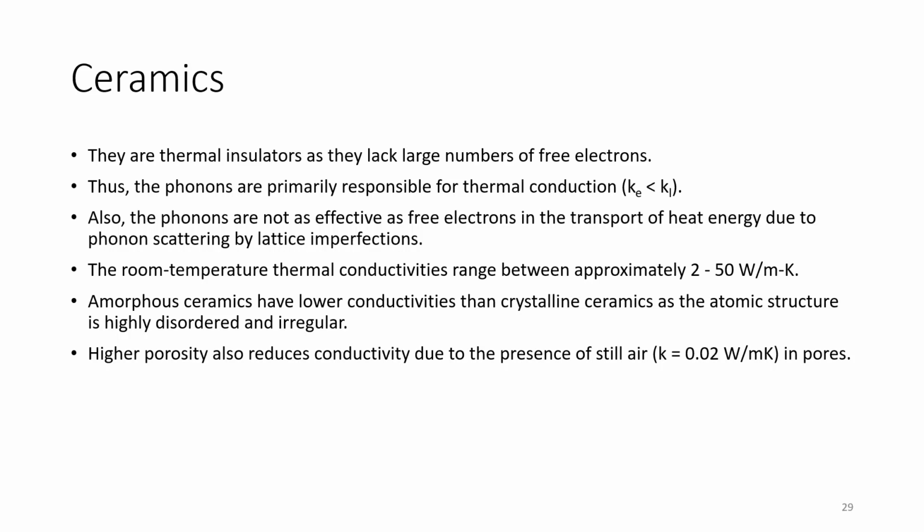Next are ceramics. They are thermal insulators as they lack a large number of free electrons. Thus the phonons are primarily responsible for thermal conduction. In this case conductivity because of electrons is lesser compared to conductivity because of phonons. Also the phonons are not as effective as free electrons in the transport of heat energy due to phonon scattering by lattice imperfections. The room temperature thermal conductivities range between approximately 2 to 50 watt per meter Kelvin.